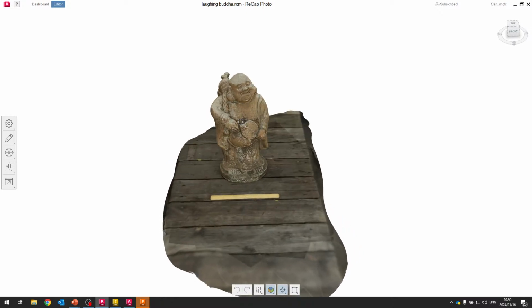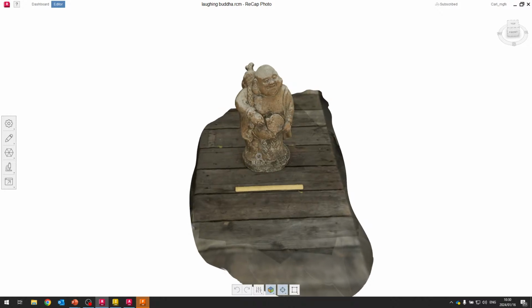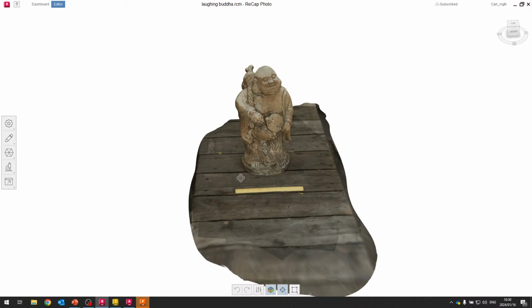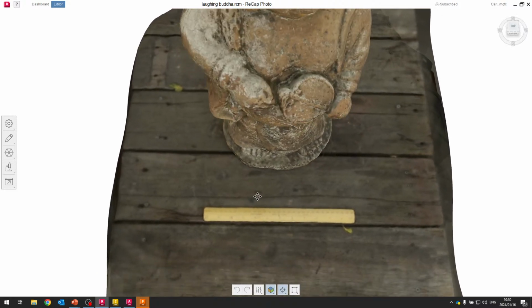I've had pretty good results. If you're thinking about the scale of scanning a swimming pool and the surrounding area, I've scaled using a step that was about 1.5 meters, 1.6 meters wide. So scaled that to size, and on the opposite side of the swimming pool, dimensions on that side of the pool were maybe within a couple of millimeters. And so the scaling is quite reliable on this. So if you're doing smaller objects, your scaling or your tolerance will obviously be a lot better.